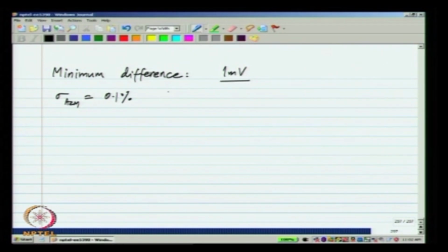So, that means that for 99.9% of the amplifiers, the common mode gain magnitude will be less than 0.3%. Now, there is nothing sacred about this 99.9%. We will just assume that if only 0.1% of the amplifiers fall beyond this, we will throw them away and use only the ones that are within this range.